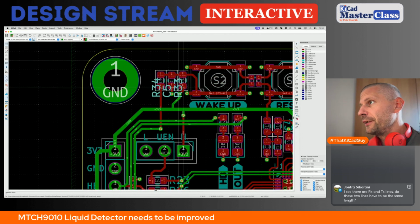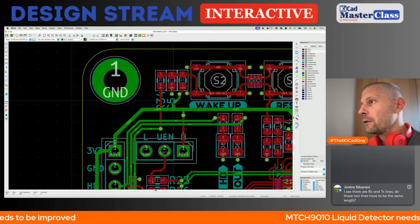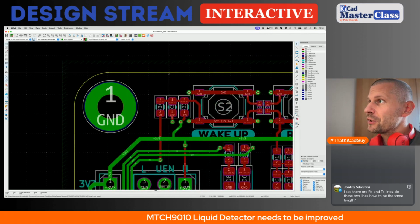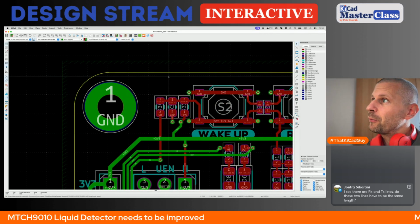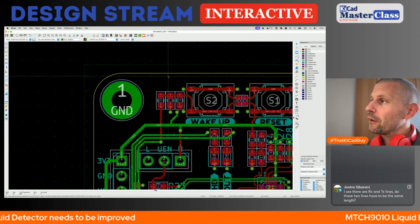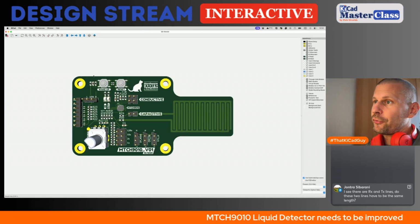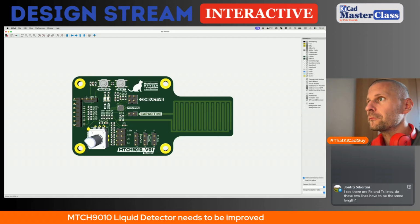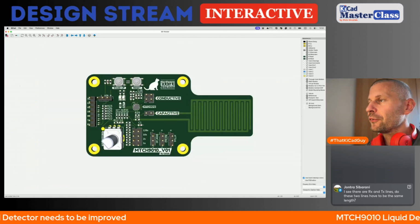These three labels are too close to the board edge, because there is some constraint that the label mustn't be so close. I think 1 millimeter or 1.5 millimeter for the manufacturing, and I don't want to have the cut labels. So this is definitely better. So the conductive and capacitive. Okay.